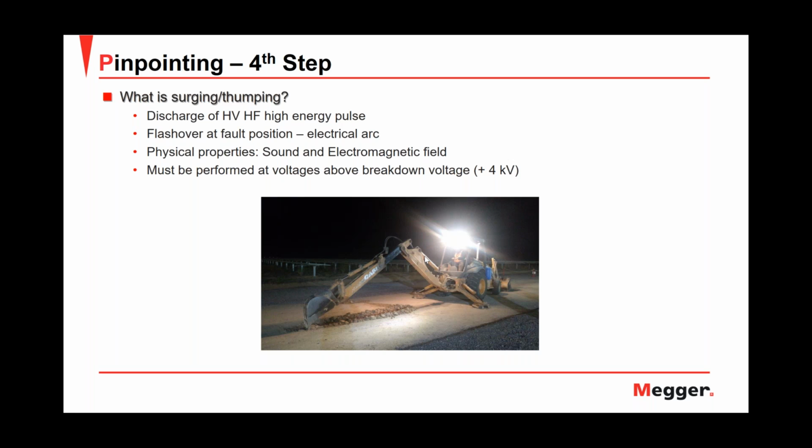There are two signals that I want to pick up: the electromagnetic signal and the acoustic signal. And we need to perform the pinpointing at least 4 kV higher than the breakdown voltage. For instance, if the breakdown voltage of my fault is 1 kV, I should thump my cable with at least 5 kV.